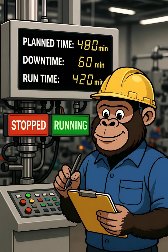Now here's what most people miss. Availability only counts downtime during planned production time. If your machine is scheduled for maintenance on Sunday, that doesn't count against availability. We're only measuring when you plan to produce, did you actually produce? Breakdowns, changeovers, material shortages, waiting for approvals, all of that is availability loss.